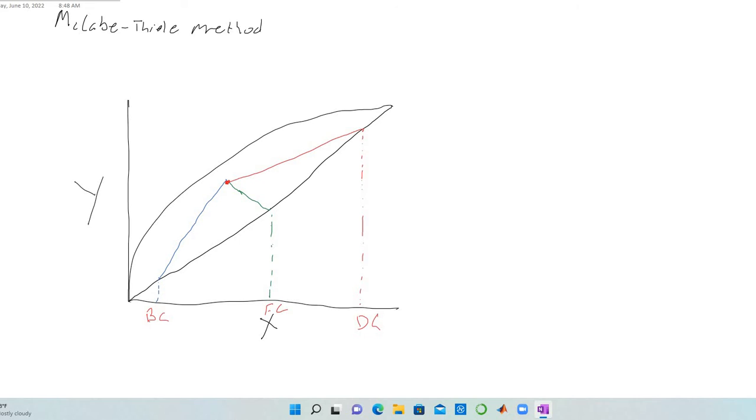So in order to count the stages, we're going to start at the operating line, go up and intersect equilibrium, and go back across. You always want to start and end on an operating line, and you're just going to go through until you're out of line, right? So see here, this is a partial stage, so we cannot count it. So that means we have 1, 2, 3 stages involved.